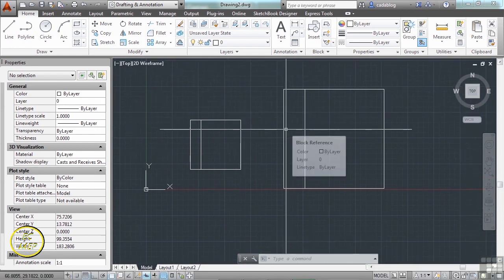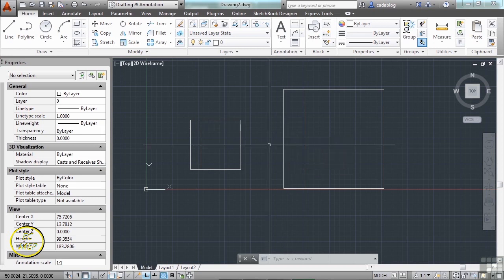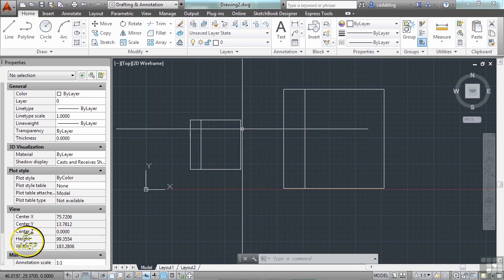Now, it's a normal practice to use the coordinates of 0,0 as a reference point for a lot of different things. Site plans, architectural drawings, surveys, etc. Inserting a title block and other items at 0,0 is also a common practice, especially when you're working in paper space. And when you create your block, keep in mind that every block's insertion point is located at 0,0 of that individual block. Also, once inserted, a block can be copied, moved, rotated, etc., just like any other object.